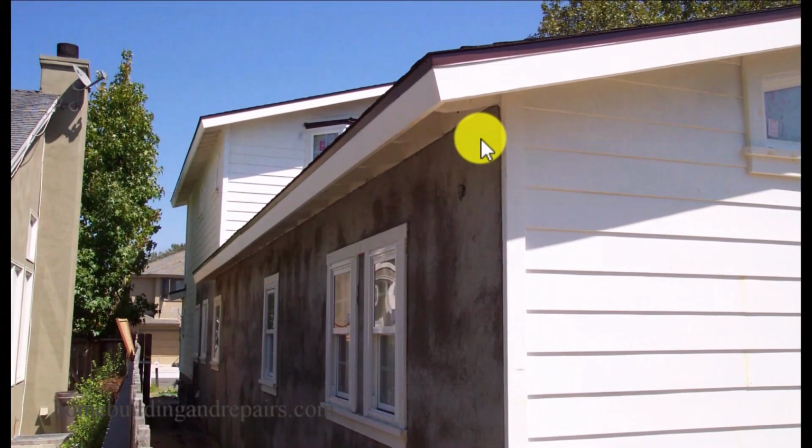And the last tip I want to provide you with in this video, and it might not work all the time because you might be dealing with a different roof, would be to drive around your area to see if you can find a roof similar to the one you're planning on building, and then check out the materials they used for their overhang, for their roof rafters, and for their seat cuts if you can see them. If not, at the very least, you'll have a pretty good idea about the material sizes to build a 2-foot or a 16-inch overhang for a roof in your area.